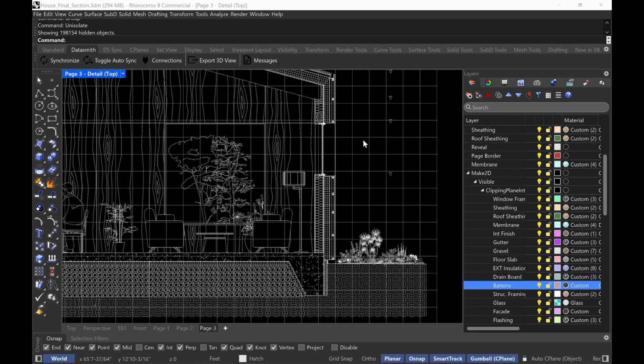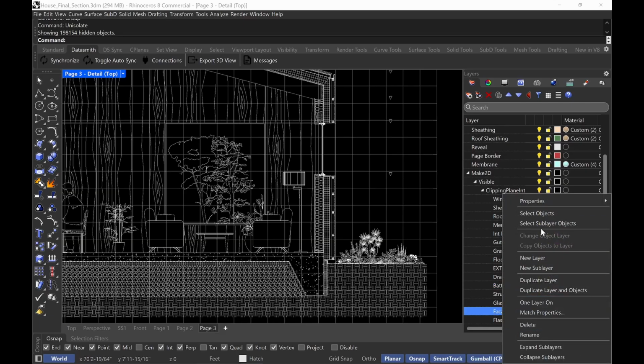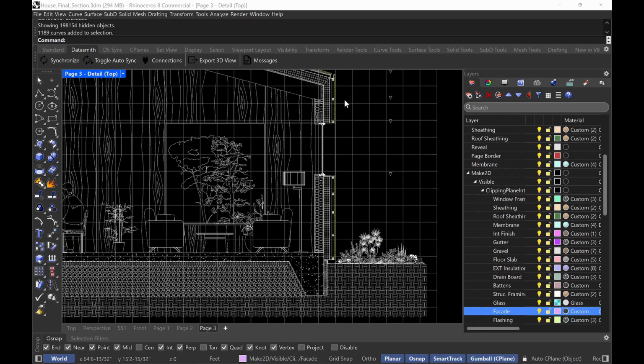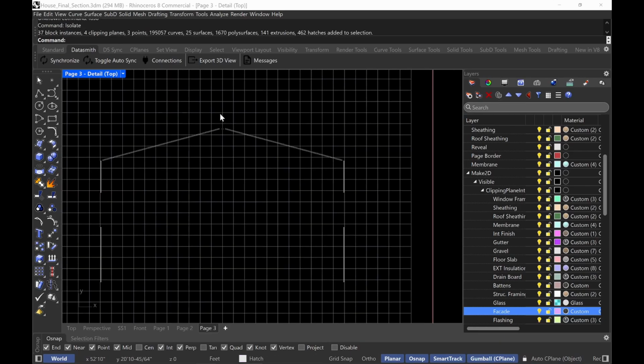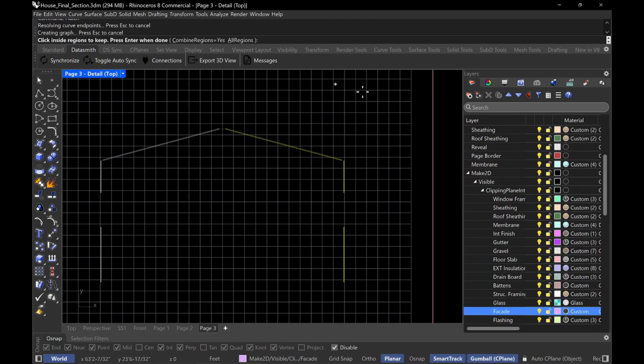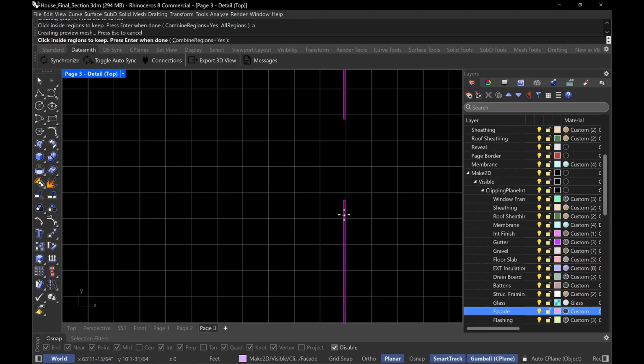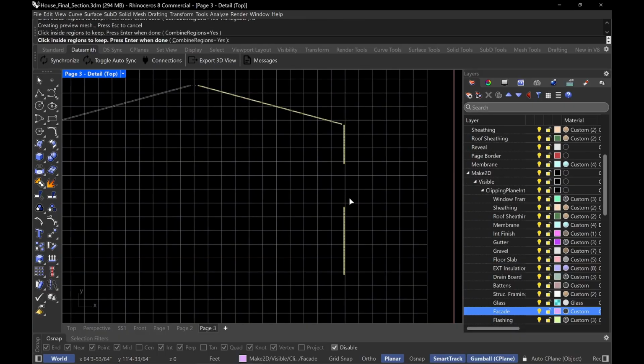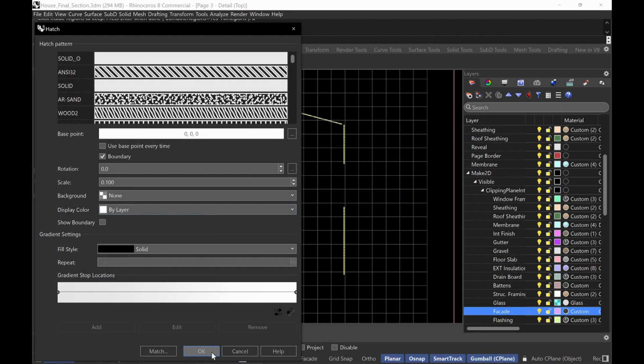So for example, when I do my facade, I can go on facade, select objects, right? Isolate. You see that? Then I can just select these. Again, ignore this. I would only do half of them and then mirror everything else. Then do hatch, right? I can do A for all regions, and if it's not closed, I can click inside the regions that are bounded, right? Enter. Exact same dialogue, just do OK, then you just cell hatch and group, okay?